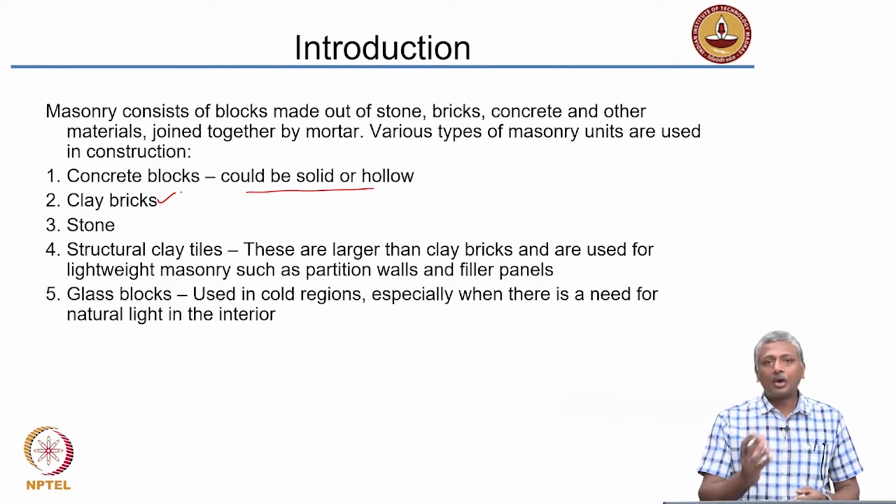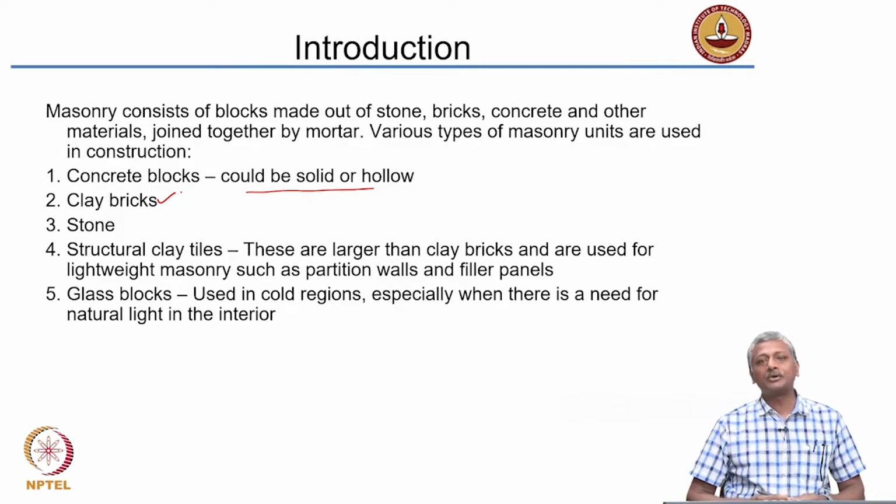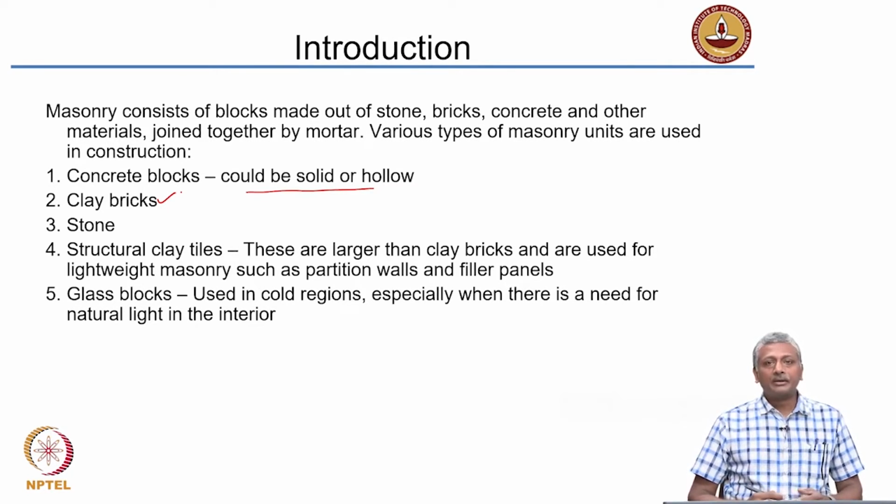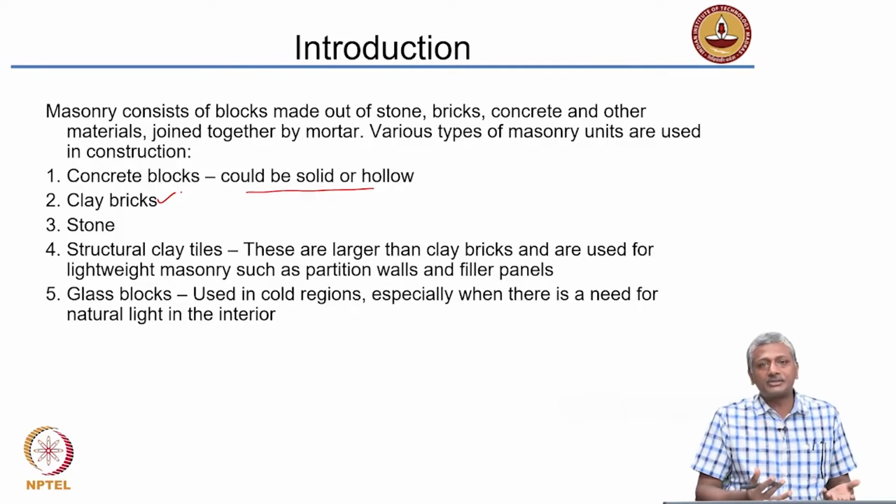Okay, so a lot of these designs are obviously the domain of architects, which civil engineers typically don't really design or engineer masonry structures. And that sometimes could be a problem, because especially when you talk about earthquakes, if you don't engineer masonry structures well enough, in an earthquake there can be very severe damages. In many of the earthquakes, the structures that completely collapsed were the ones which were built with masonry. And that's because they were not engineered, they were simply constructed.